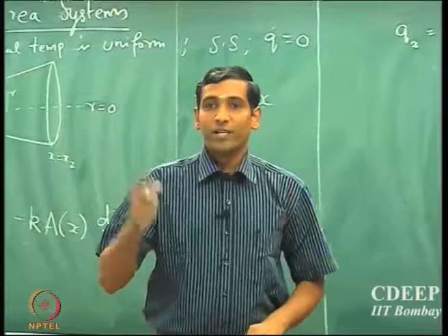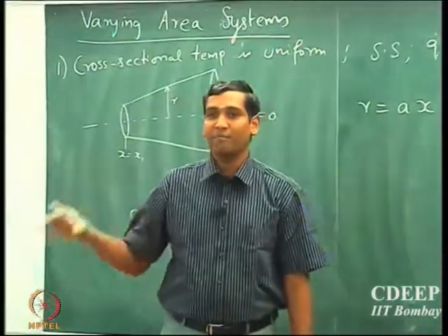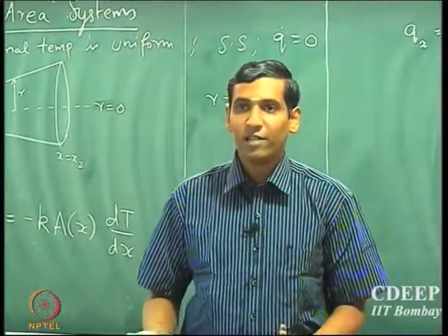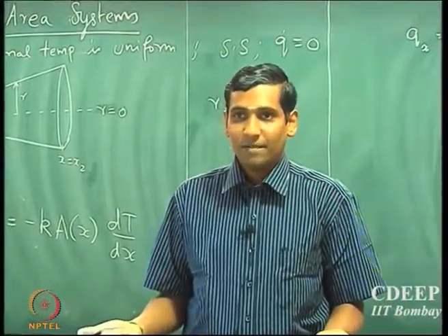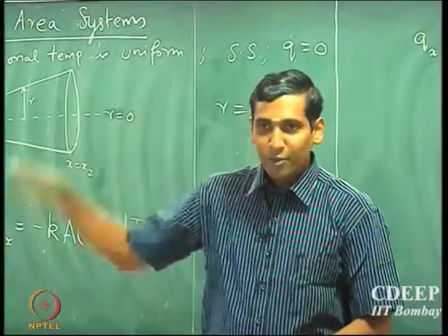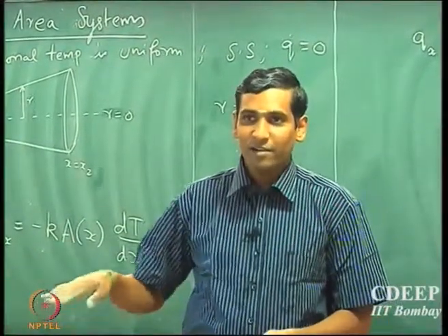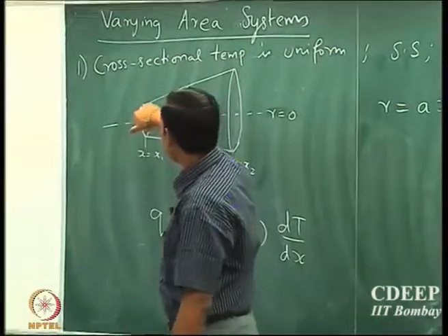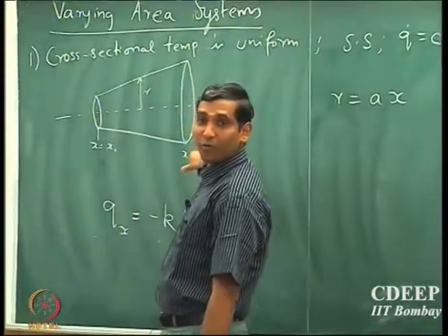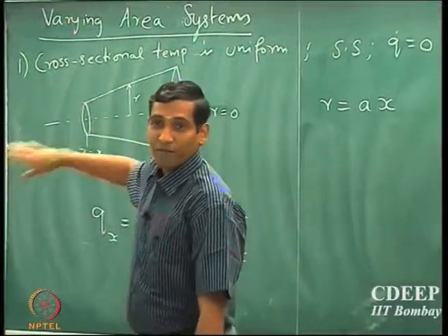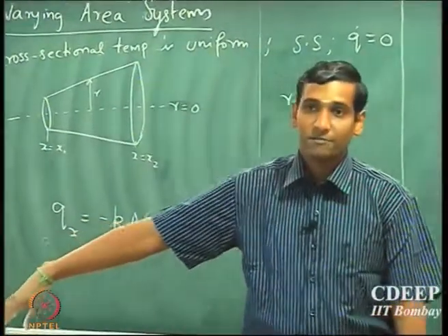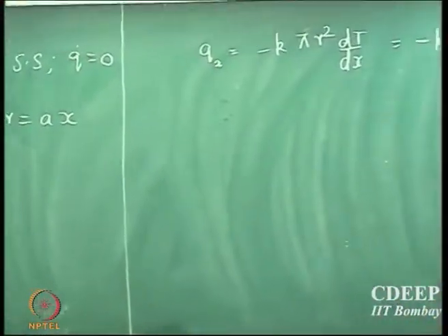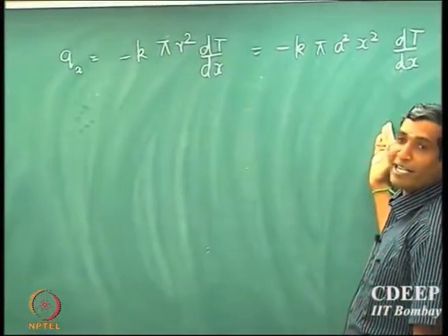Right. So the question is, if you have dissipation of heat, how will it be constant? But when we say that there is no generation or loss of heat, it means that the dissipation is 0. We will come to that. There are ways to consider that. When you are doing a two-dimensional system, you can actually look at dissipation from the outside walls, and we will see it in one of the examples in future lectures. Alright, so because Qx is constant, we should be able to integrate this expression to find the temperature profile.